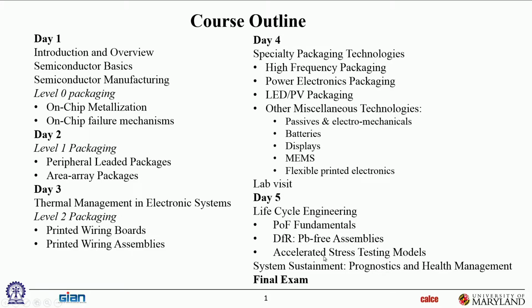And then we'll use those same models to look at how people design accelerated stress tests. Obviously, you have to qualify your products in the lab in an accelerated, shortened period of time, right? So you have to mimic a 3-year or 5-year or 10-year life cycle within a few weeks to a few months in the lab. How do you accelerate those tests or accelerate those failure mechanisms in a controlled manner? We'll talk a little bit about that. Again, each of these is like several days of lectures. I'm compressing them into just a couple of hours.